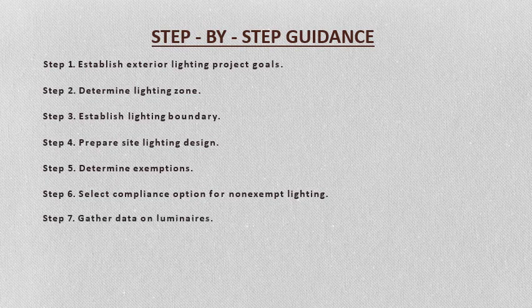Step 7. Gather data on luminaires. This could either be done by listing the backlight, uplight, and glare ratings of each unique luminaire for the orientation and tilt specified in the project design, or by showing the total lumens per luminaire and lumens emitted above horizontal by each luminaire.